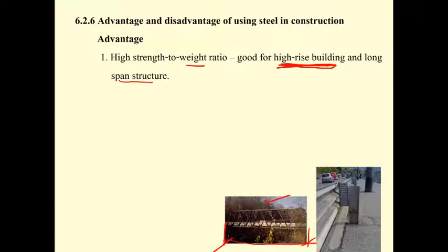And if you build it in a rough area, in the mountain area, it's hard to transport the concrete to the construction site. So steel is better: fabricate it in the steel plant, put it on some 10-wheeler truck, some semi-trailer, and move it into the mountainous area. Or even use a helicopter to deliver it.